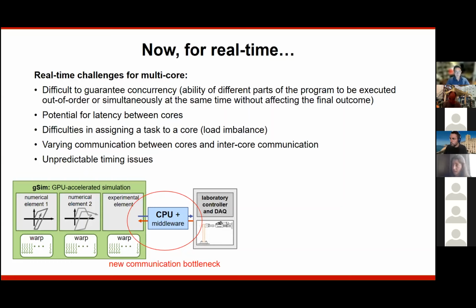Right. And if it's truly explicit, it's all matrix multiplication. There's no inversion at all. It's all multiplication, so it goes pretty quickly, I think. We'll see how that works out for us. When you look at the literature, most of it is with explicit time integration schemes for that exact reason.